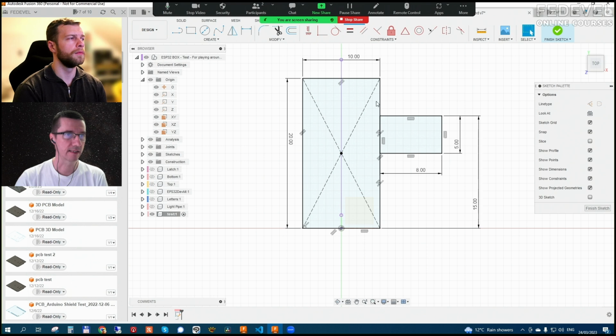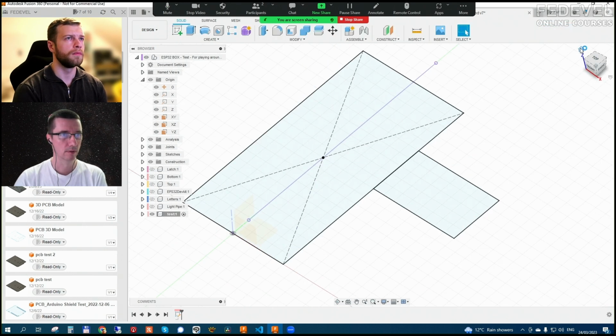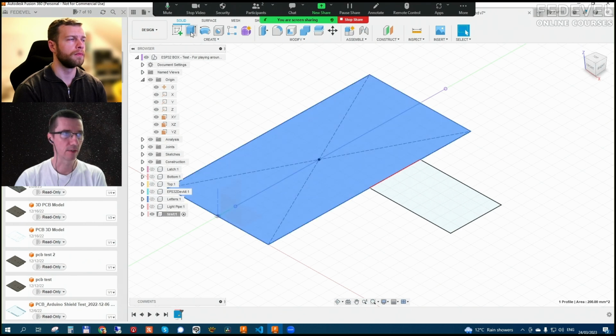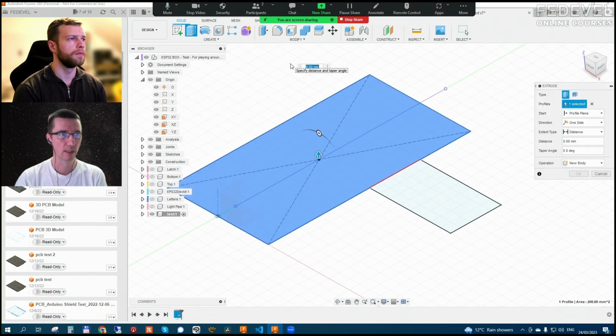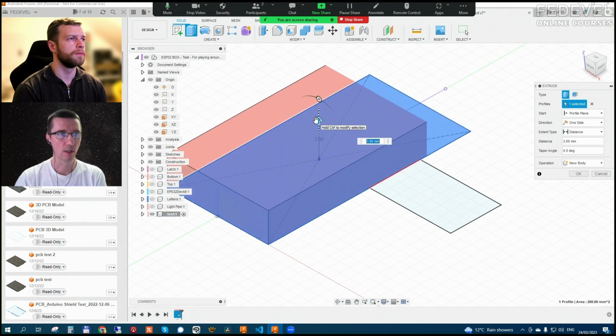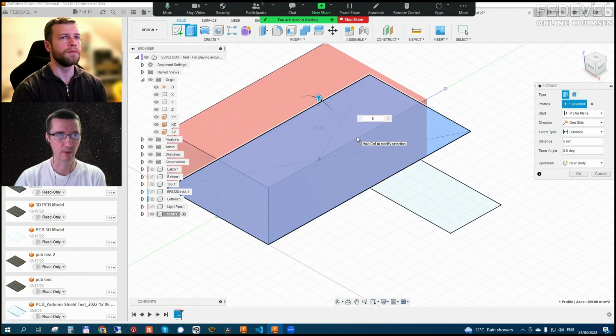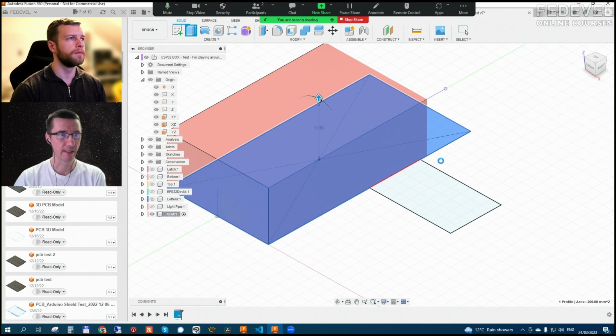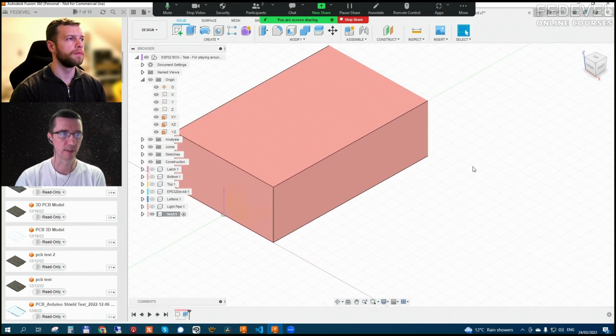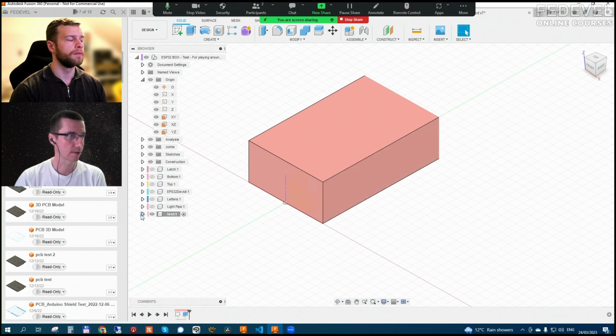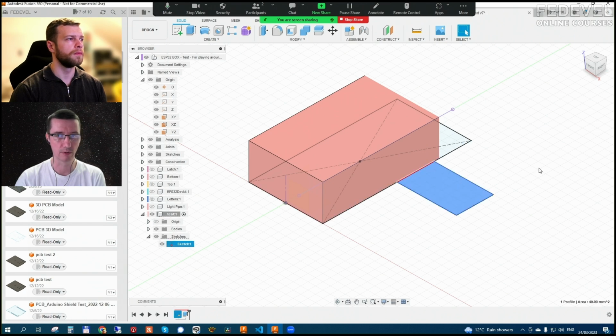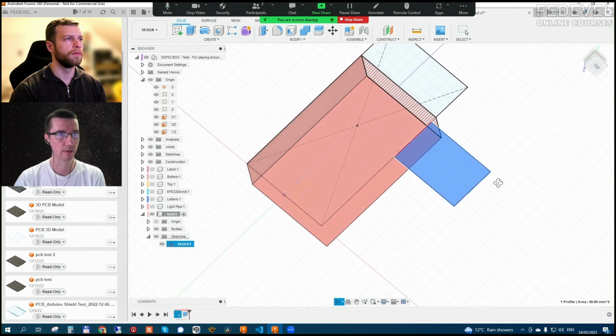Okay. And the sketch is important because from the sketch, you can then draw the 3D objects. So if you finish the sketch, then you can select these surfaces, and this is what I usually use, extrude, and you can just move it, or you can put there like 5, for example, and it will make the brick, or what is it? See? And notice the sketch disappears, so you have to make it visible again if you would like to continue drawing or doing something.